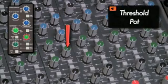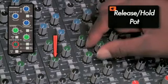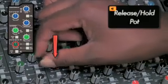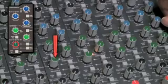The threshold pot allows you to set the level at which gating takes place. Next is the release and hold pot. This pot determines the recovery speed and is variable from 1 millisecond to 4 seconds. The release and hold pot also allows you to activate a fast attack.